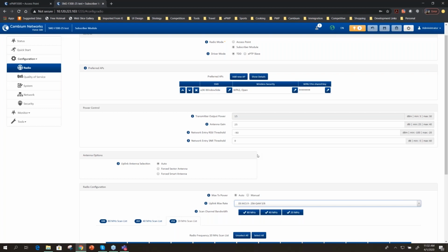Last but not least, transmit power and antennas. Making a system run really well, despite all the features, boils down to the gain of the antennas, transmit power, et cetera. Sometimes too much power is also bad because you may interfere with yourself if you're trying to use the same channel. So horn antennas are a nice use case, as we talked about earlier from a product perspective. Fewer side lobes, better front to back, directionality, alignment, all of these play into tweaking the network.